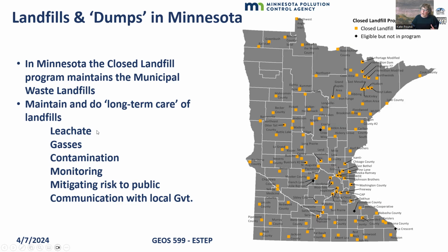First of all, there's leachate. This is the word used for the mostly waterborne potential contaminants that move through a landfill and have collected contaminants. Sometimes there are chemical reactions within material in a landfill, but regardless, you can think of it as a pollutant soup that develops, and dumps need to manage that. Then there are gases given off by the landfill. How do they manage that? Broadly, the management of these two gets rolled into dealing with potential contamination of groundwater or the air.